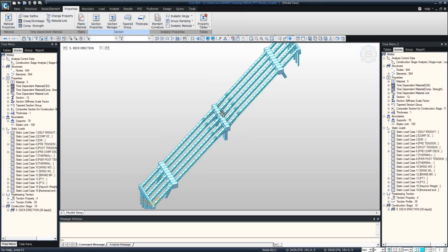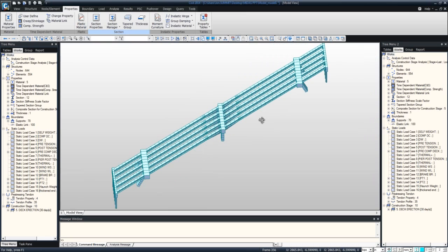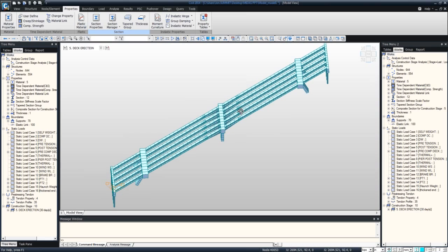We reduce rather than reinforcing for the entire element in its full stiffness, we assume that it will develop some minor cracks while still allowing the structure to remain in static equilibrium. Allow the pier cap to rotate and still stay stable.